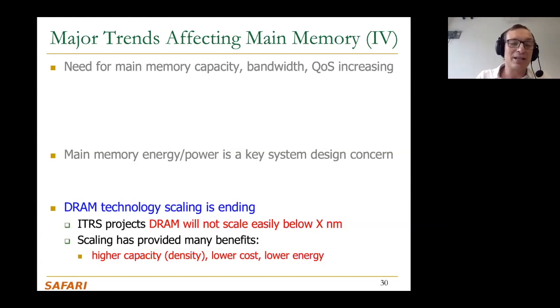And there are other issues in Moore's law today. Basically, lithography is a big issue. How can you etch things on a wafer? It has become limiting. It's limiting the scaling today. And also energy has become a problem in Moore's law, for example, in logic and transistors. As you scale the size of the logic, energy is not reducing as much because you cannot reduce the voltage as much; you hit limits in how much you can reduce the voltage.